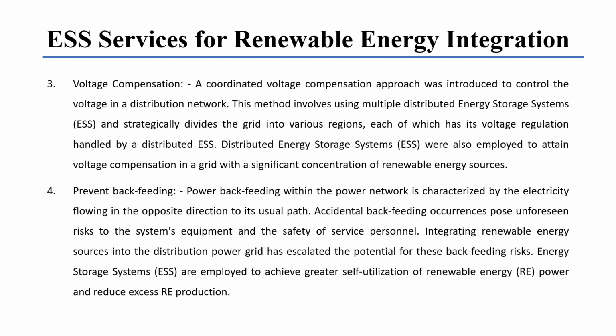A coordinated voltage compensation approach was introduced to control the voltage in the distribution network. This method involves using multiple distributed energy storage systems and theoretically dividing the grid into various regions, each of which has its voltage regulation handled by a distributed energy storage system. Distributed energy storage systems were employed to attain voltage compensation in grids with significant concentration of renewable energy sources.